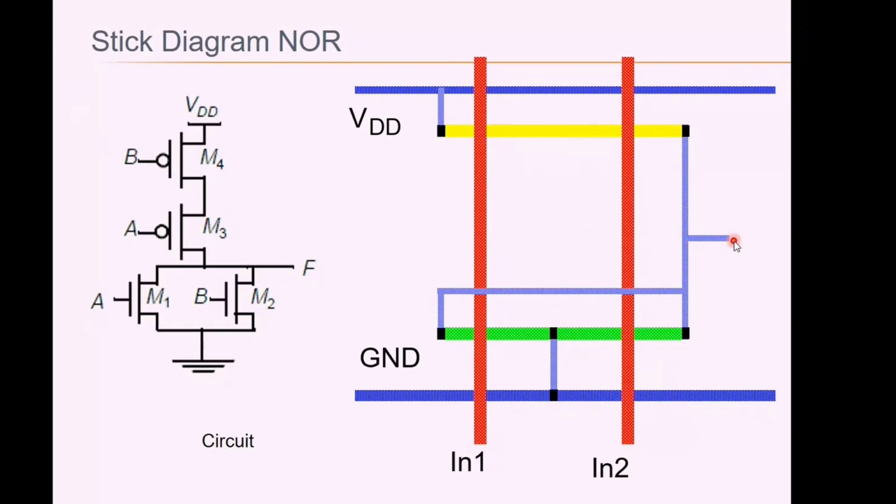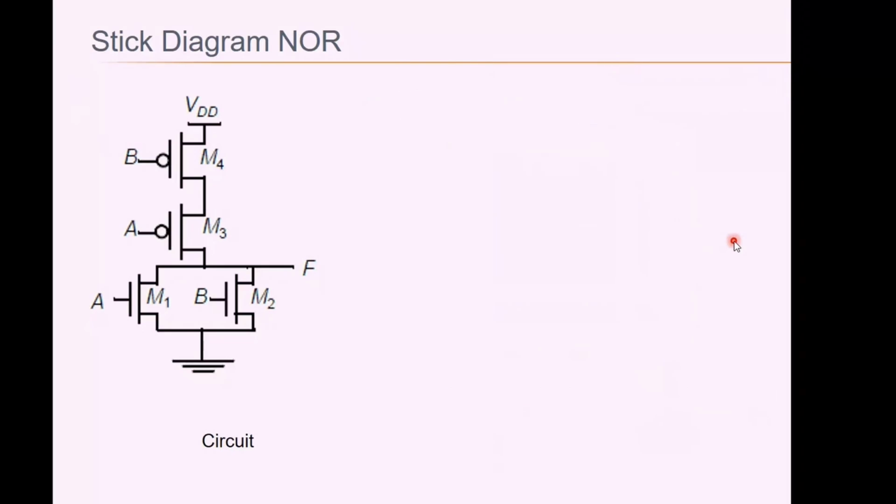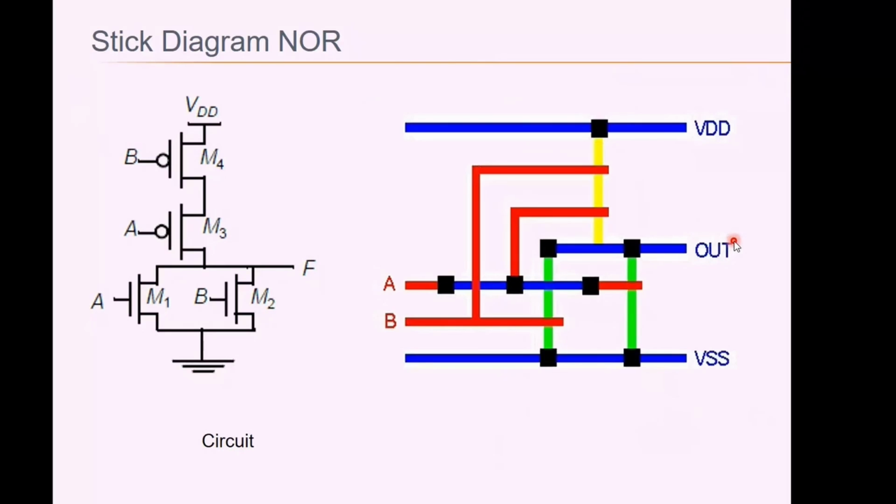Accordingly, we can choose source and drain. We can choose either side of the polysilicon as source or drain. It is not necessary to fix source and drain. We can interchange. It is not the only way to draw the diagram. We can draw it this way also. Here, this is another type of connection. Two NMOS devices in parallel.